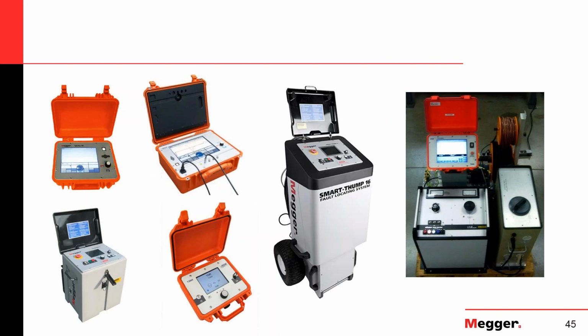So what has Megger to offer? Just a few things. On the left, you can see some radars, TDRs. Then in the left lower corner, it's the Easy Thump. It's a small thumper, 12 kV system. In the middle, you see one of the bigger units, a 16 kV dual stage thumper, 1500 joules. And on the right, you can see a system that is